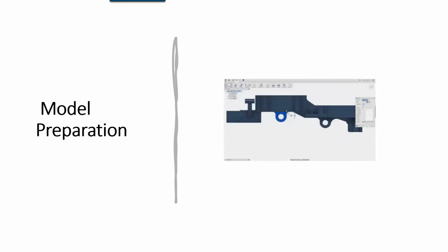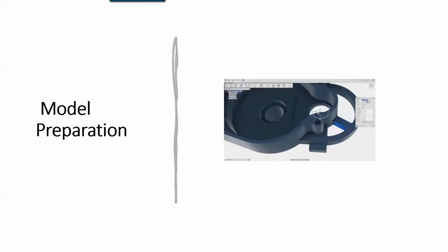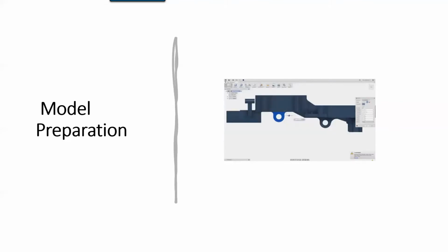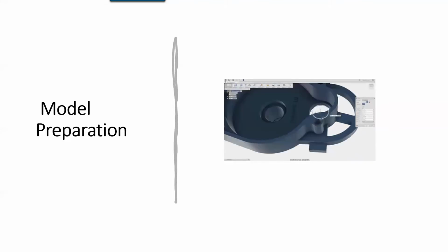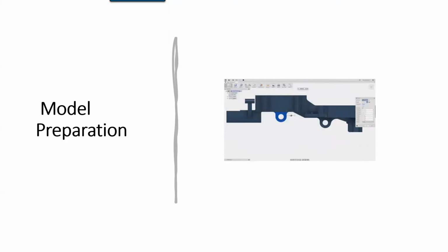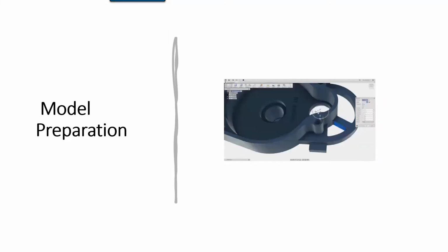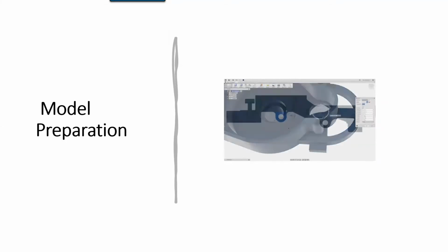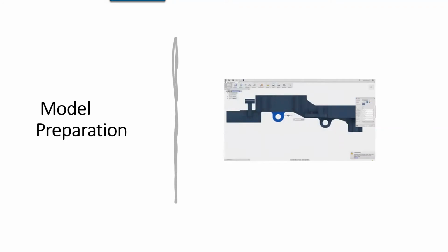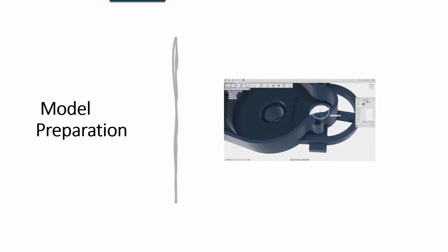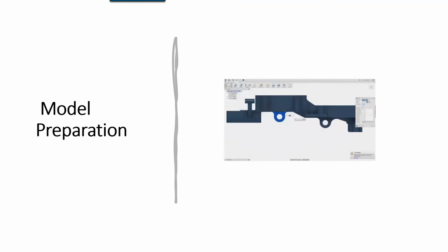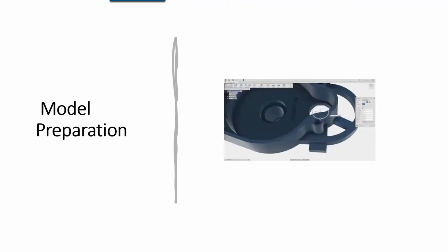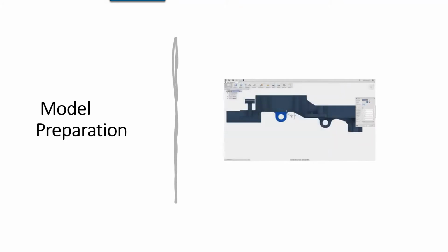You don't need any of the design history, the sketches, the extrusions, the holes, any of the features that come with it. You can automatically select geometry and make modifications to it relatively quickly. A little bit different than some of your more traditional CAD software, in the sense that it lets you modify this data without needing the history that was required to create that model.